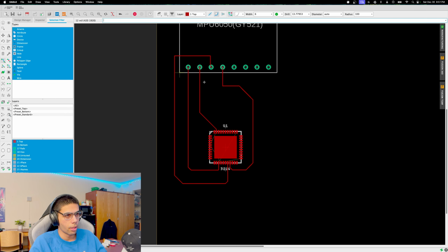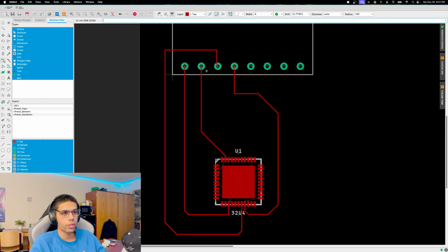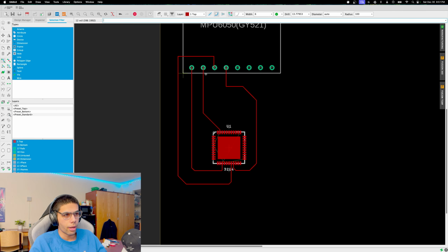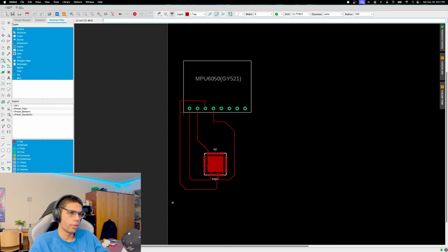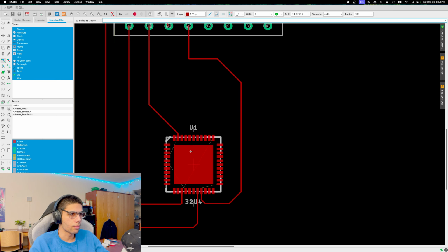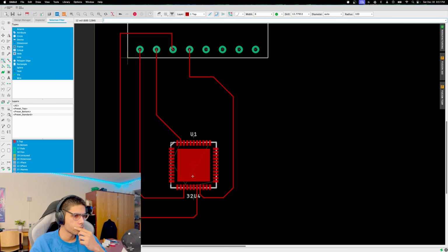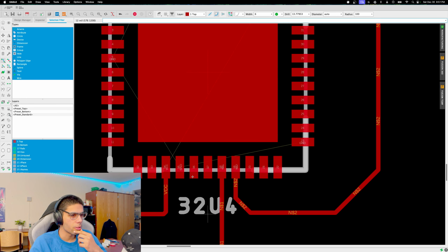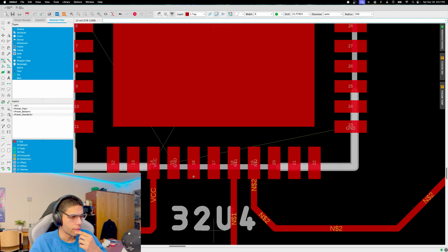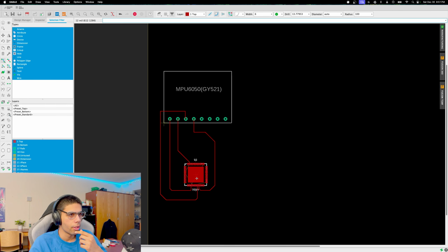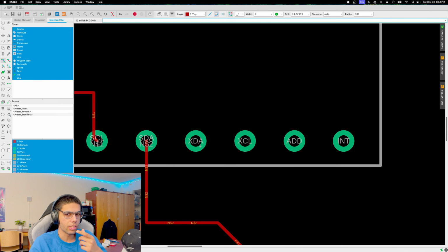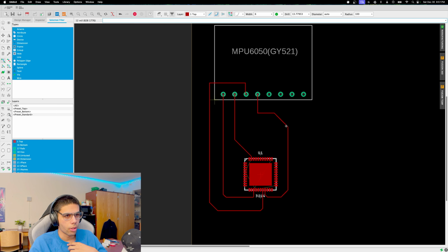Now imagine that there's one more connection that you need to do, and there's no way around. Even this way behind is not available. So what can you do now? So what we do in that case is, let me show you one case. So let's say I want to connect this pin, the 16 pin, to this pin, SDA.